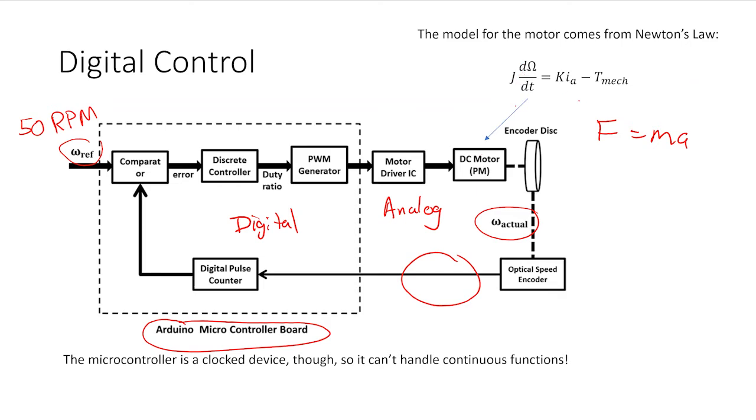All right, now without getting into the physics of that situation, I don't really want to get into the physics. This is the net torque. This is the torque produced by the machine. And this is the torque that is trying to slow the machine down. So it makes some sense if you think about it. There's a torque produced by this thing that's related to the current going through it, okay? So basically what I get is a first order differential equation, all right? That first order differential equation describes how that motor works.